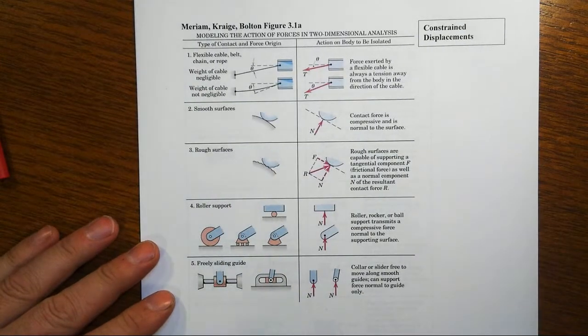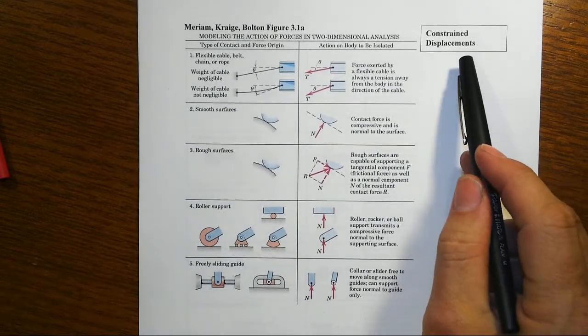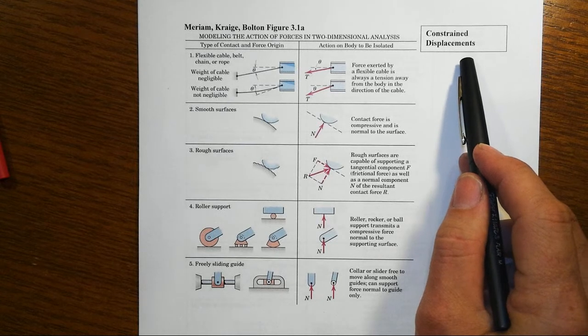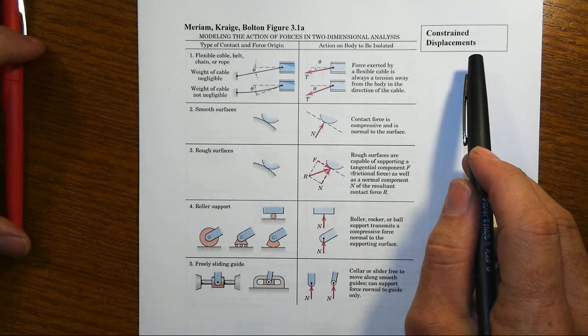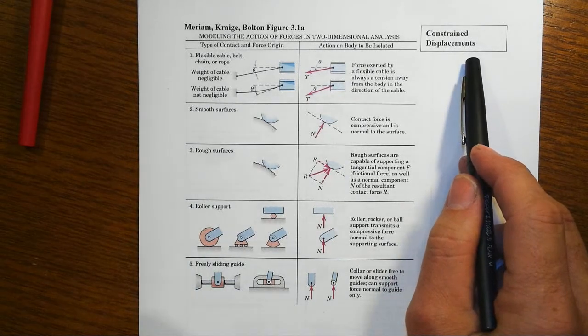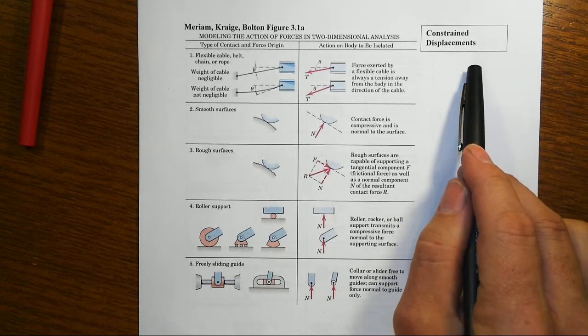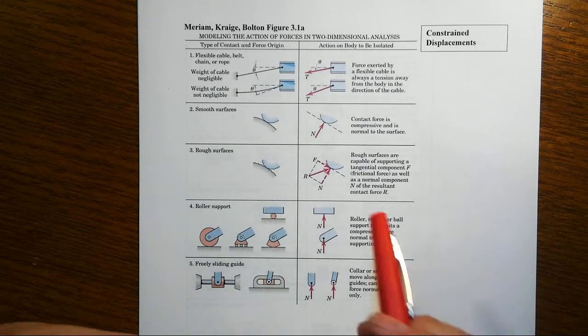Those are the three basic ones. There are a lot more of them out there, but it's all in the end going to be associated with what displacements are constrained. That is the absolute final key. And you won't hear a lot of people talk about that. They'll say reactions are the forces necessary for equilibrium. That's true. However, a more general statement is that they're the force necessary at that specific point in the structure so that a specific displacement is zero.